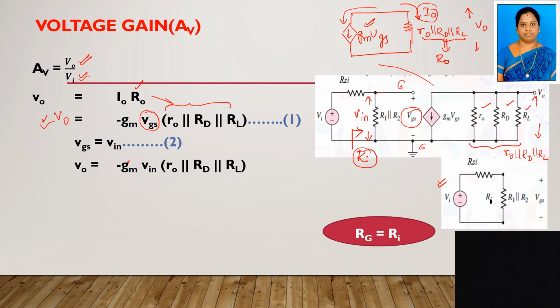So you can compress the whole circuit. For example, if you have it like this, you just compress the whole thing to this side. Here you already have the resistance, and here it is the voltage source. So if I compress all the circuit together, when I'm looking from here, I'm having the resistance of Ri. So I'm drawing the same diagram with Rsi and this input voltage, right? Looking from here, I have the resistance Ri. That's why the circuit came like this.